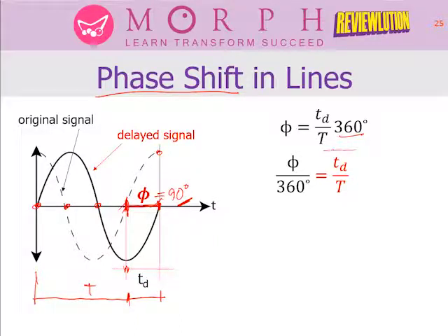No? So by using this formula, kahit ano pa yung hahanapin, as long as the two other parameters are provided, wala nang problema. Halimbawa, hahanapin yung phase shift, may time delay and period ka. So alam mo na yung phase shift. Multiply mo lang yung time delay over the period times 360. Or halimbawa, meron kang phase shift, tapos binigay din yung period. So you can now solve for the time delay. So as long as meron tayong tatlong kompleto and isang unknown, we can always use a ratio and proportion for solving that item.